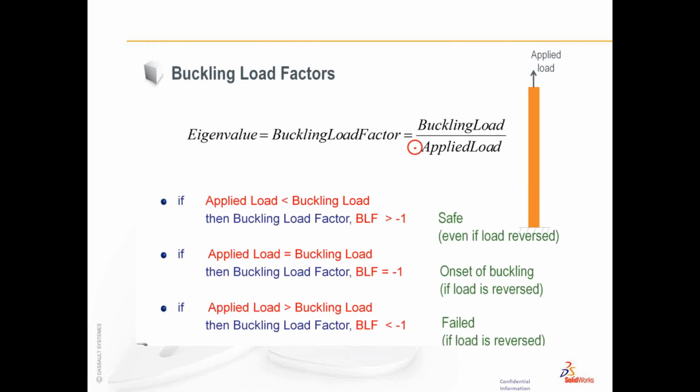Another interesting extension of that is a negative buckling load factor. And this would happen if we have an applied load that is a tensile load as opposed to a compressive load. Now, structures don't collapse from buckling due to tensile loads. Tensile loads actually tend to increase the buckling strength or the stiffness of a structure. And it's very similar to a frequency study. If anyone has done frequency analysis, you know that if you put a structure in compression, the natural frequencies tend to decrease.